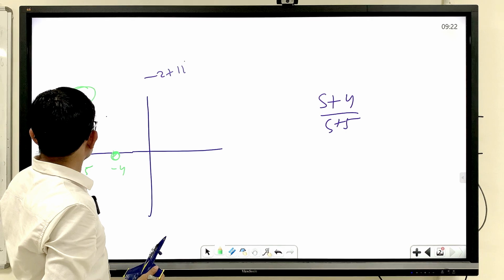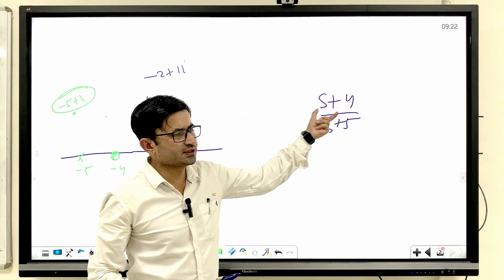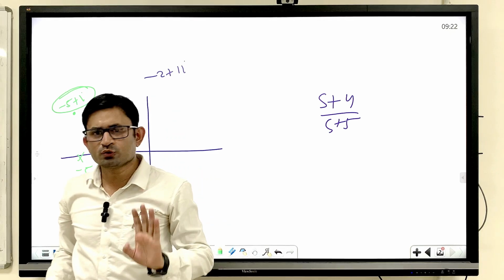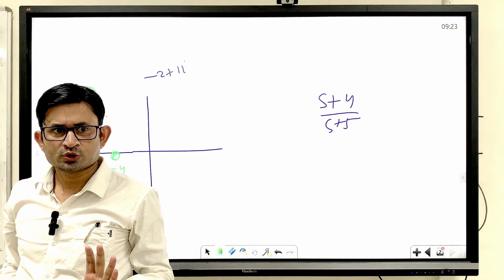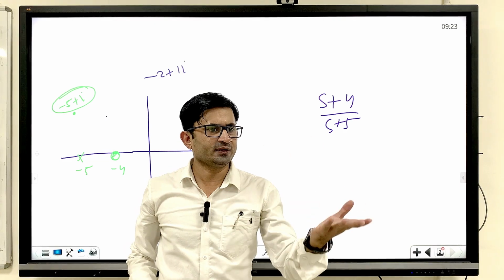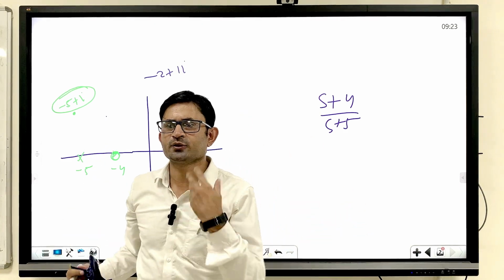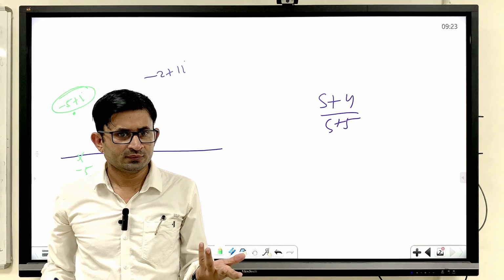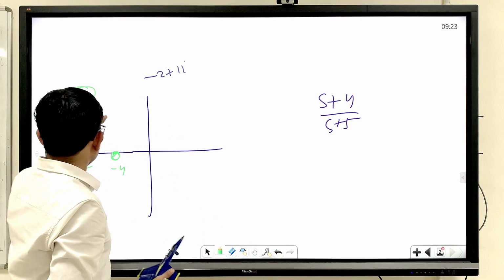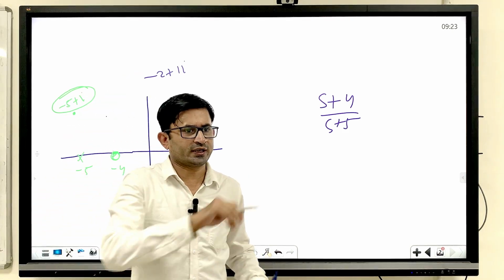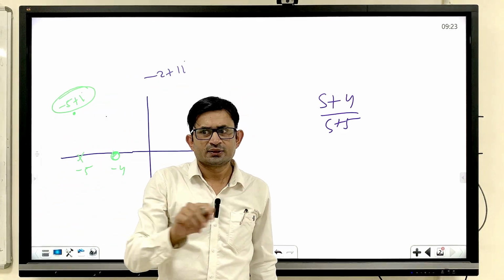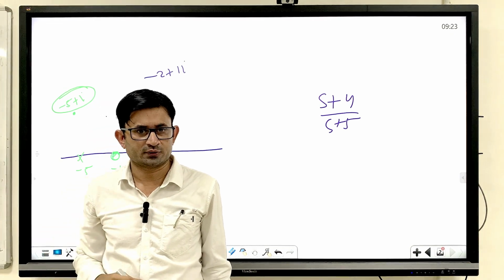If you put this 5 plus i in this transfer function, you get a new complex number. So you can plot it in a different plane. This is the S plane, and that plane you can call the S dash plane. And if you keep repeating this, and you track all the points, that will be the Nyquist plot.